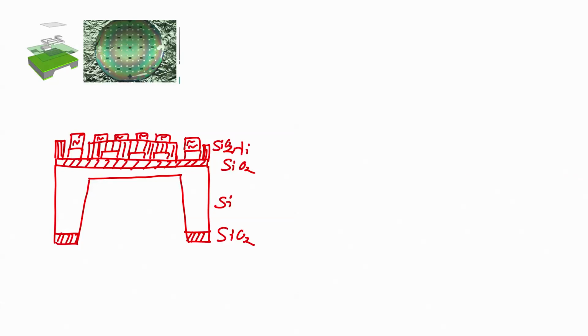Okay. Now, instead of performing a standard photolithography, I will show you something called lift off technique. What? Lifting off, lift off technique. This kind of technique is used when you think that the etchant of the top layer will affect the bottom layer below it. What do I mean by that? Let us see here.